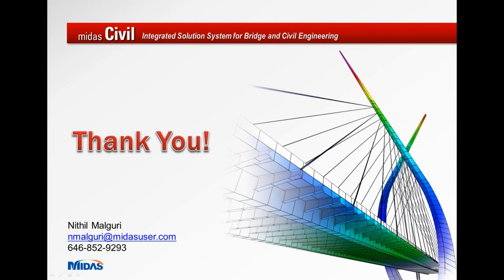So for the clay it was 0.45 in the actual model, and the one in which I have used the same, it was just for demonstration purposes, because I just wanted to tell you how the soil type can change the effect on the bridge. So I kept all the parameters same, but I just wanted to make sure that only the soil type is different, because when we obtain the spring stiffness, it depends on what type of soils we have in the model.